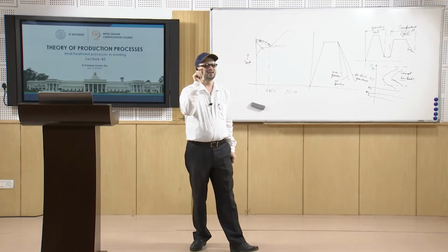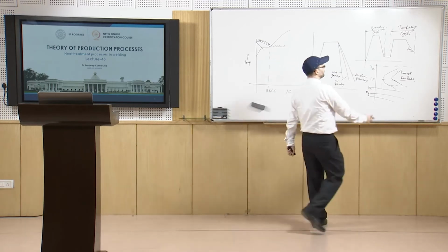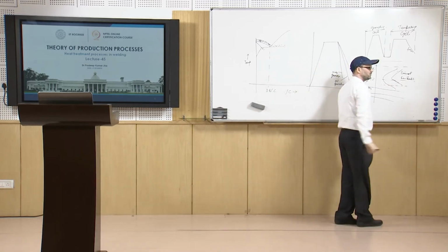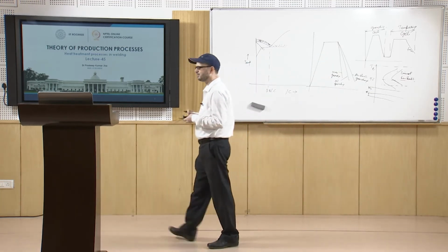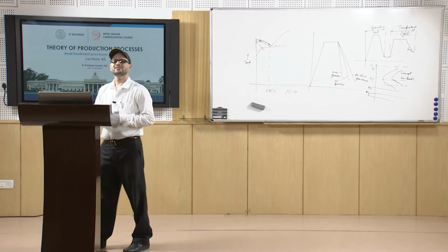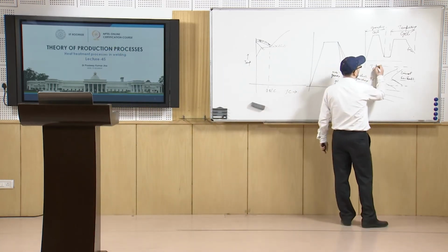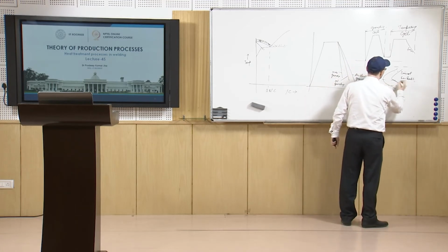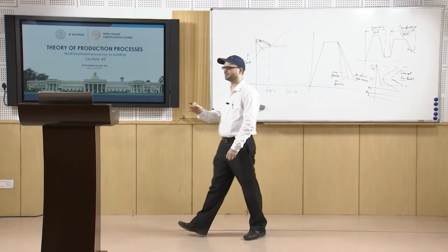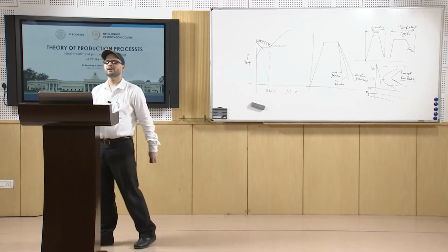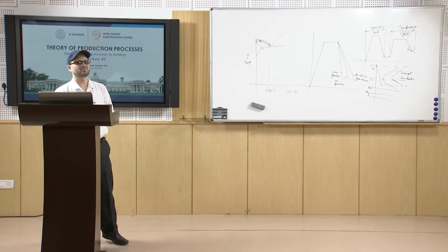It is a very needle-type structure. So you have a coarse structure on this side and a fine structure towards the lower side, and that structure is known as bainite. It has very good toughness. In this treatment, you come to this temperature and hold it there, and you get the bainitic type of structure. This treatment is known as the austempering treatment.